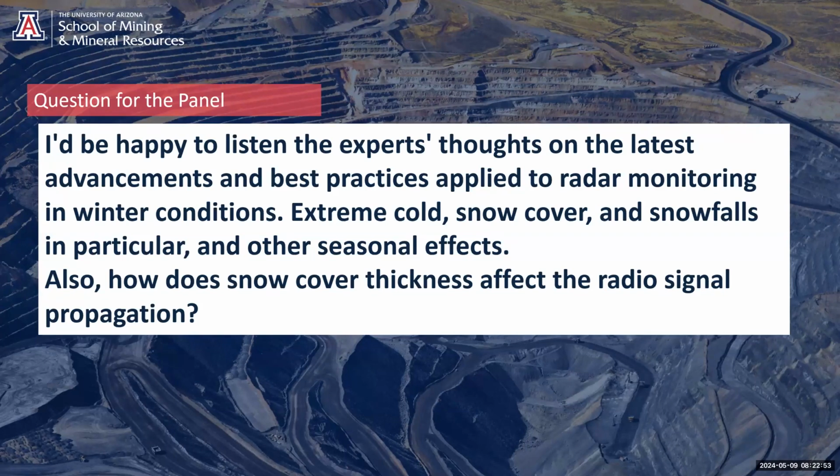So in those complex scenarios, I always hunt for pixels of good quality through the coherence parameter. We have had, with a recent algorithm, Precision Atmospherics, some good success at Bingham Canyon, for example, and Mount Wright in ArcelorMittal, Canada, during the snow periods, in which the algorithm managed to still produce reasonable data and maintain in the maps during the winter some of the trends detected in the periods without snow.